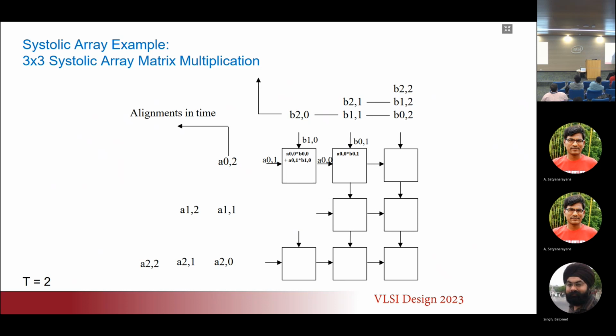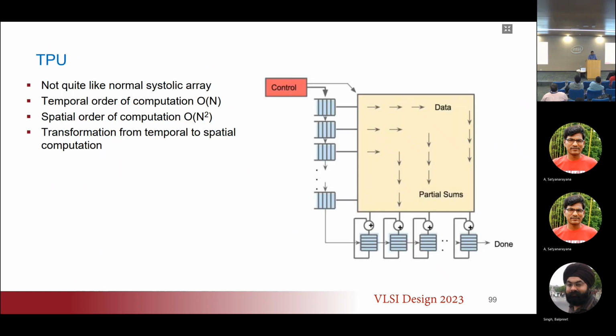So in the accumulator, this value is already sitting there, but now I take this value and that value, multiply them together, and add it back to the accumulator. So it has this result. In the meantime, A00 shifted here, and B01 shifted there. So I multiply them, and it's here in the clock cycle. So now I apply another clock, and it keeps going that way.